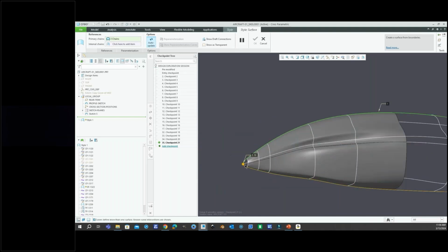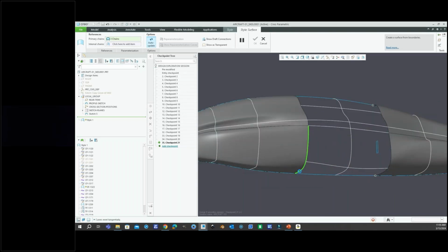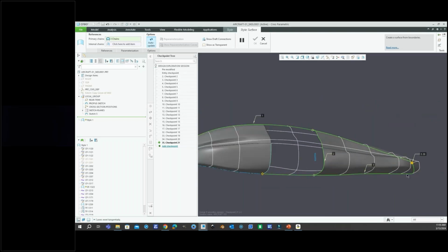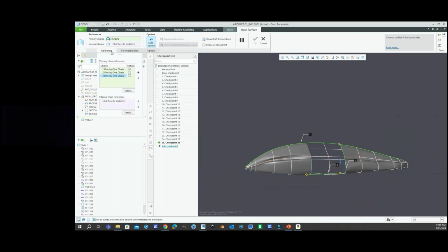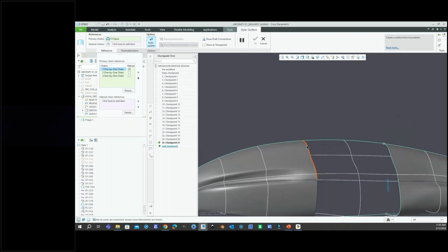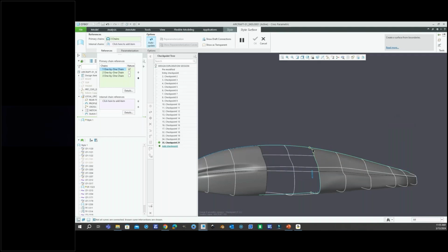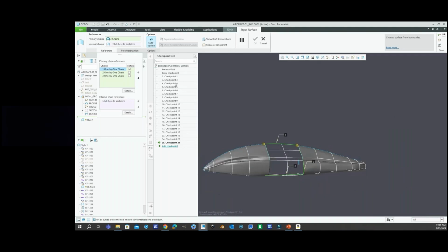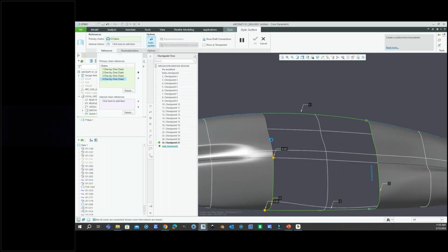These four here. I can easily trim this too. I can say, hey, let's trim this curve here at that spot using that line as a reference. Trim at, and I like to just kind of make sure I'm keeping this stuff clean. And I can even go back here if I want to, right, select chain one, do the same thing here. I'll trim at that edge, and then trim here as well. Okay, so I've got 3 curves selected. I'm going to need this 4th one. Hold Control, then hold Shift to get the rest of that edge.